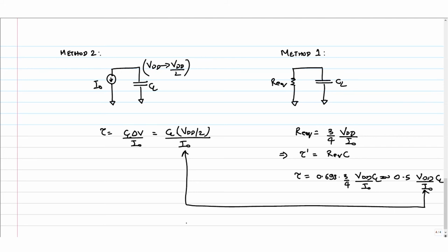right. Now obviously if lambda is 0, then the constant current source model is the right model, because the transistor is a current source. Okay, so if you look at the model that we are using for delay, this guy, if you look at this V naught of t, it will start from VDD and then go linearly, right. What is this? C dV by dt equal to I, so I naught by C into t.